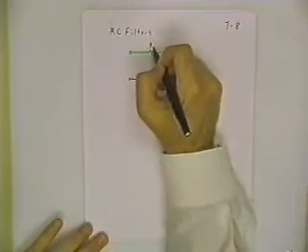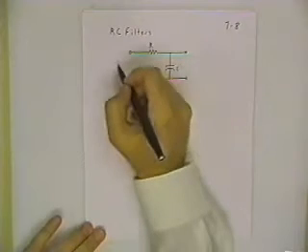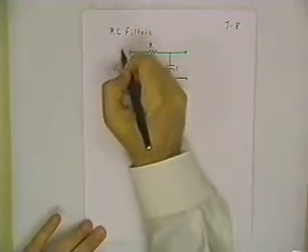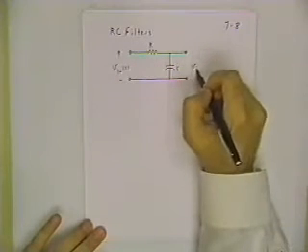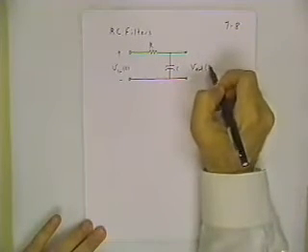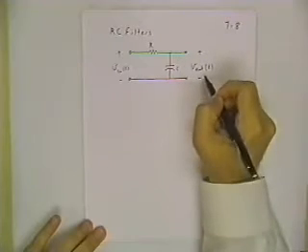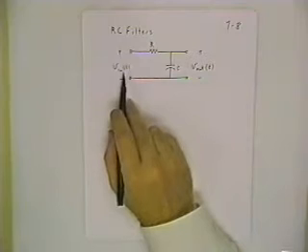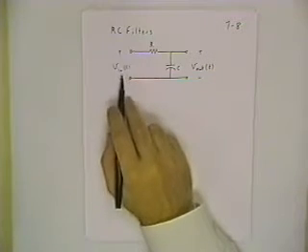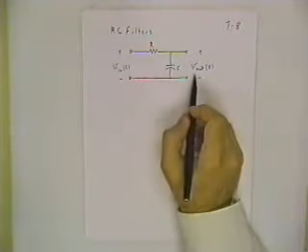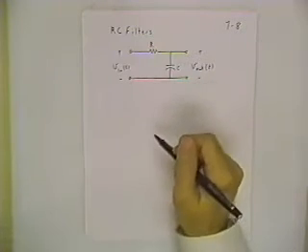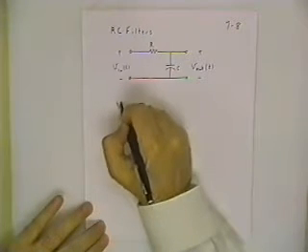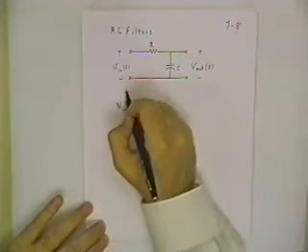But now we're more interested in how does this circuit respond to different frequencies as I take the input sinusoid, compare it to the output sinusoid. So you have to imagine that you're looking at this on an oscilloscope. And then let frequency increase. Start at 0 frequency and increase through larger and larger frequencies, and ask ourselves what happens to that output waveform. Well, to figure this out, what I want to do is go over to the phasor form, V in.